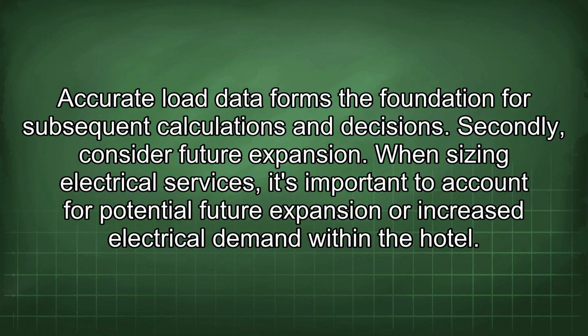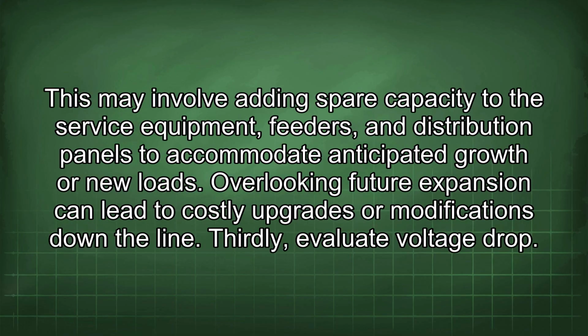Secondly, consider future expansion. When sizing electrical services, it's important to account for potential future expansion or increased electrical demand within the hotel. This may involve adding spare capacity to the service equipment, feeders, and distribution panels to accommodate anticipated growth or new loads. Overlooking future expansion can lead to costly upgrades or modifications down the line.